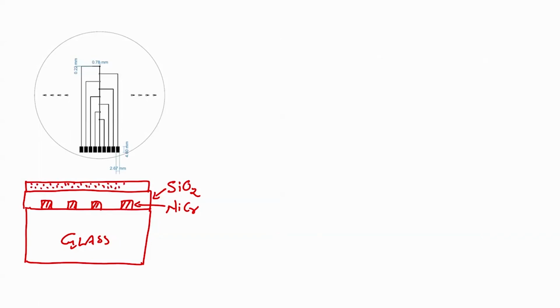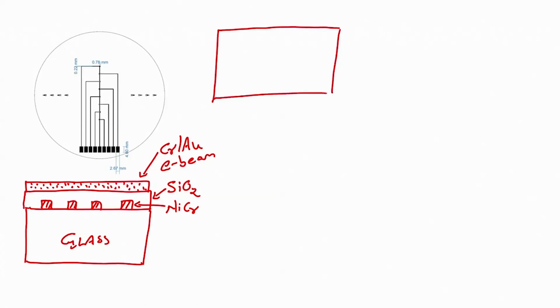metal for interdigitated electrodes. So, let us say I have chrome gold as the interdigitated electrodes, right. How can I deposit this metal? You can deposit either by E beam or sputtering, E beam or sputtering. What is the next step? My next step would be to start the photolithography process, right. So, what is the photolithography process?